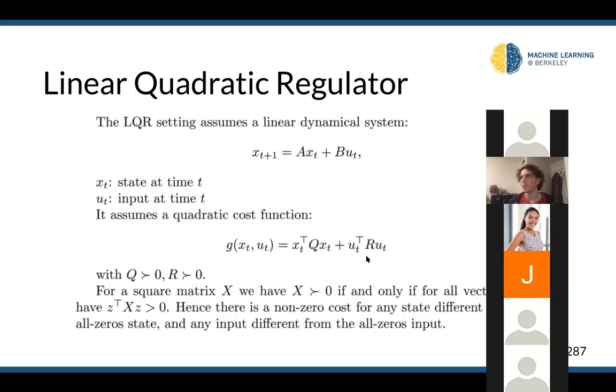action. And say we don't really care if our car turns a lot, but we care if it slams on the gas. Then this is sort of like PID tuning, to be honest. It's part of the problem definition. This is not something we compute, this is just something we put in. And they're all relative, so what really matters is the relative values of these different elements. So we can say we really care about minimizing situations where we slam on the gas, but we're okay with turning a lot. Then we can have a higher constant for throttle than for steering. And what you would do is run LQR with that cost, see how it behaves, and see if it does what you wanted it to do.